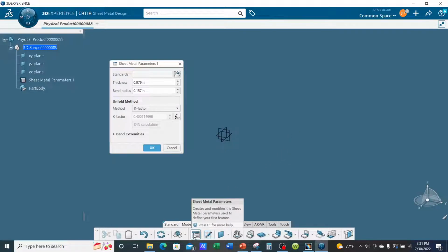So let me go to parameters here. Now, typically, if I'm at work, this would be linked to an Excel spreadsheet with different types of, usually aluminum alloys. You can also go with steel. And we would pick out from the Excel spreadsheet the material we're using. Let's say I'm using aluminum 6061 T6 aluminum alloy. And I'm going to use a thickness of, let's say, 0.063.